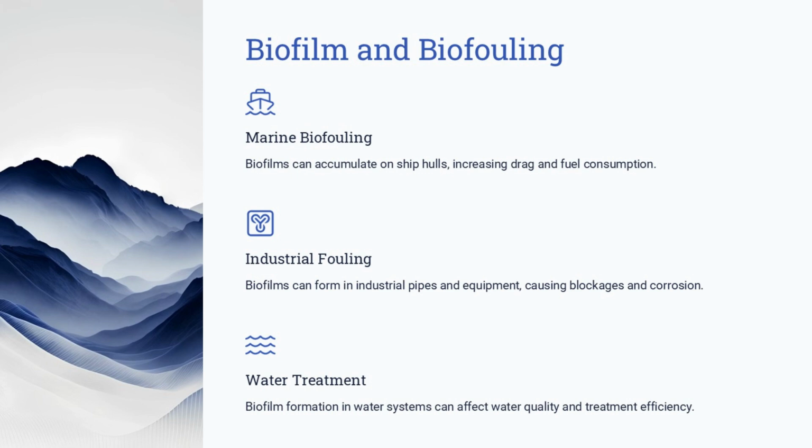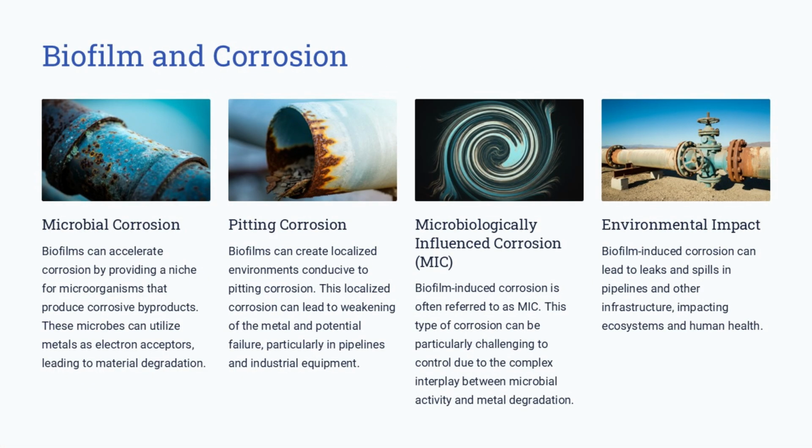Water treatment. Biofilm formation in water systems can negatively impact water quality and treatment processes. Biofilms can accelerate corrosion by providing a niche for microorganisms that produce corrosive byproducts. These microbes can utilize metals as electron acceptors, leading to material degradation. Biofilms can create localized environments conducive to pitting corrosion, which can weaken metal and lead to potential failure.